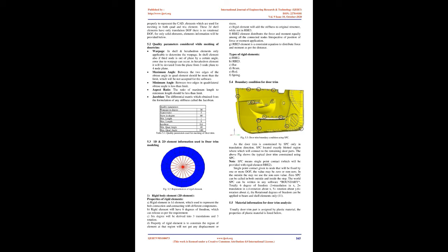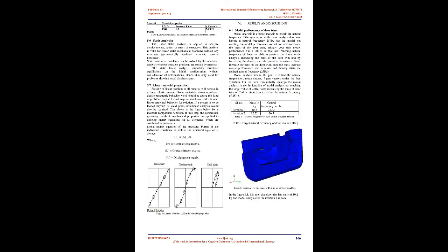3. Summarization. 1. Modal analysis of the rear and the front doors reveals that they are on target. The front door's lower opening must be split into 2. Rear door stress analysis suggests the need to extend the latch reinforcement or add a terminal flange in this area. Anti-intrusion bar and mirror reinforcement increase stiffness in the hinged area for both front and rear doors rather than for the rear door only. From the strength point of view, there is still wide opportunity to increase the stiffness of doors by increasing the percentage of ST42R already used and/or other high-strength steels without increasing weight.